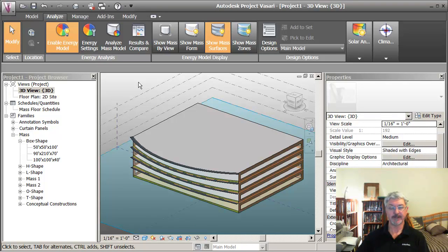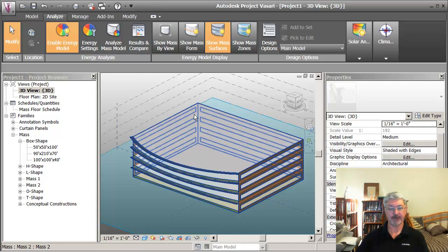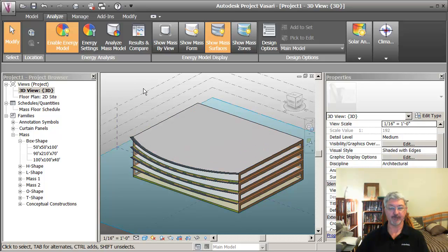That lets me very early in the design process try and establish the direction that I want to go in, and then later, of course, I can take this model into Revit and I can say to it, why don't you change this roof surface to an actual roof? Why don't you change this wall surface to an actual wall or curtain wall? So I can start on my construction documentation without me having to redo anything. I can go straight from the conceptual massing.